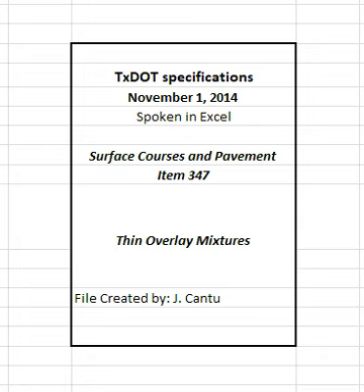2.1 Aggregate. Furnish aggregates from sources that conform to the requirements shown in Table 1 and as specified in this section. Aggregate requirements in this section, including those shown in Table 1, may be modified or eliminated when shown on the plans. Additional aggregate requirements may be specified when shown on the plans. Provide aggregate stockpiles that meet the definitions in this section for coarse, intermediate, or fine aggregate. Do not use reclaimed asphalt pavement, RAP, or recycled asphalt shingles, RAS. Supply aggregates that meet the definitions in Tex 100E for crushed gravel or crushed stone.